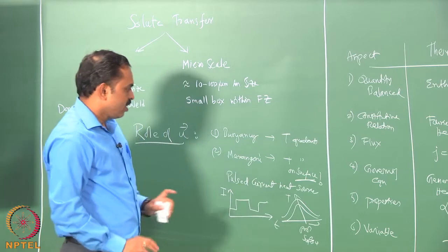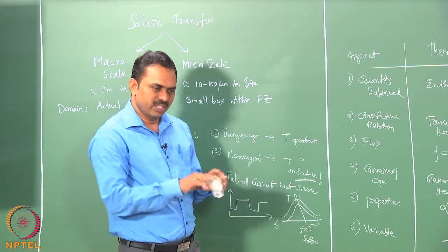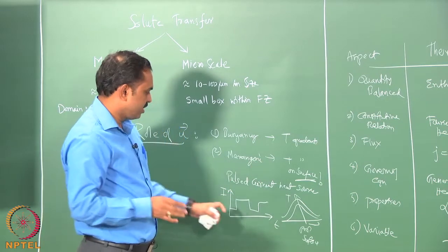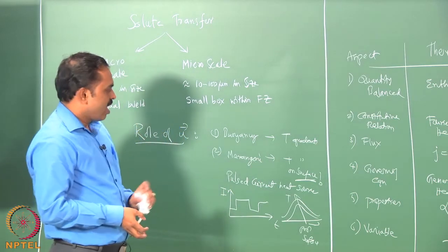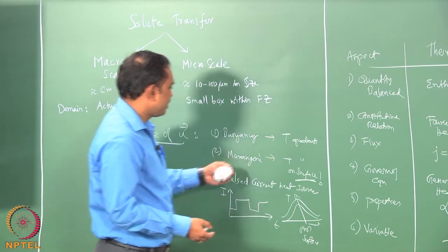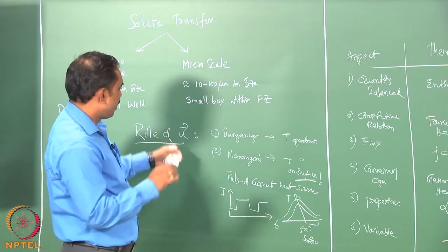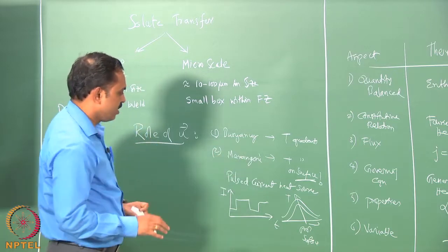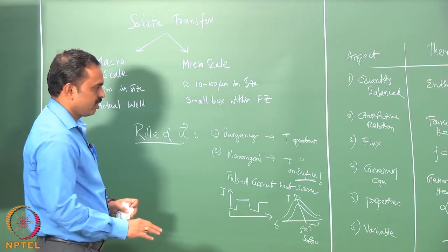So, the Marangoni convection on the very top surface is going to be fluctuating at the frequency at which you change the current, and any fluctuation implies that the velocity on the surface is going to be fluctuating by that much variation.